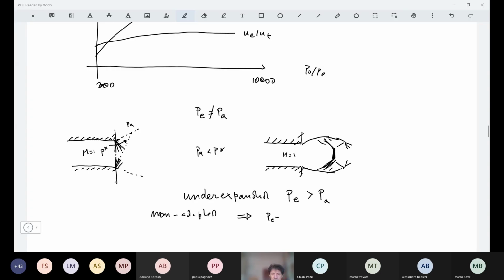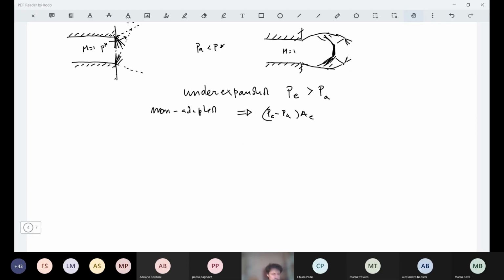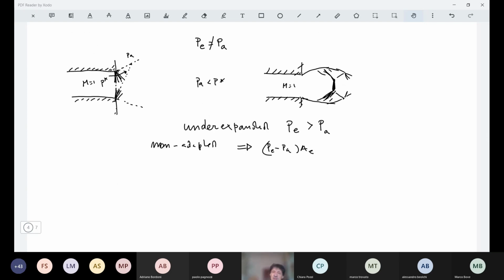So we also have the pressure term to be considered in the thrust expression. Whereas the choked nozzle is also called the saturated nozzle. So, let's now go back to our converging diverging nozzle, and we'd like to make a similar discussion. This can be considered as the final part of the former discussion we have done for the converging nozzle.